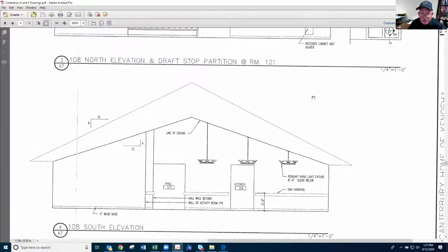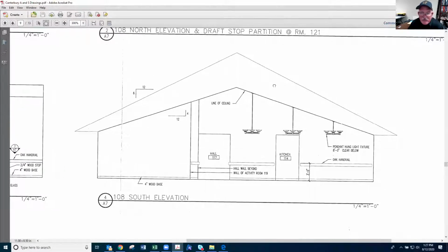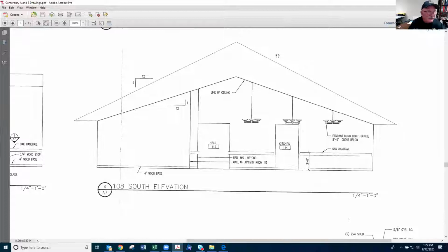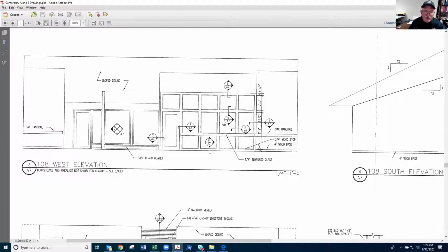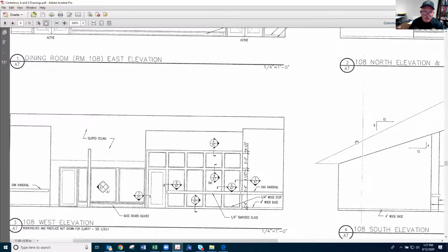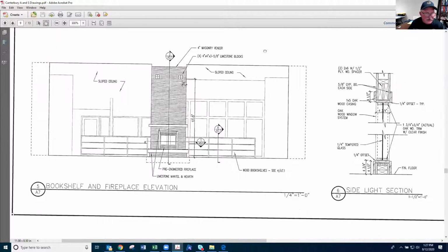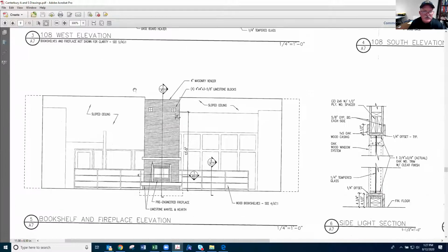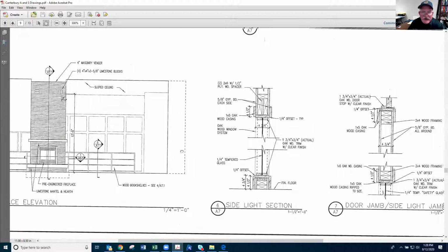It'll give us some fixtures. It'll give us things that we'll want to look for in here that's not here. Not here is basically emergency lighting, that sort of thing. You might find that a lot of times on your electrical schedules. A lot of times you'll find it on your architectural schedules too. But this tells you what it's made of, the firewall elevations, how it's bricked all the way around, the limestone blocks. Basically, it's fire rated from that, and it should be listed as fire rated, but it's not.